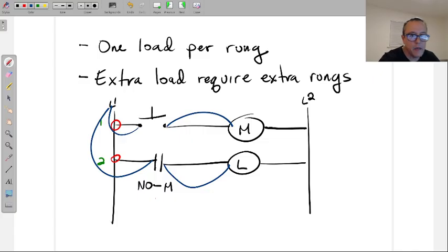Again, anytime you place a little dot and you say, hey, we're picking up the rung from there, you are now giving the option to the person who's wiring this to place the wire wherever they want. And they're not going to tell us wherever they placed it. It doesn't get a footnote on the ladder: Hey, I put it over here. You now just have to go find that thing. So something to keep in mind as you get into this stuff. But that's the reason why.